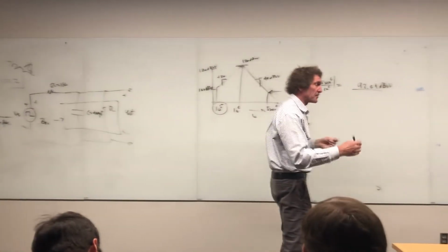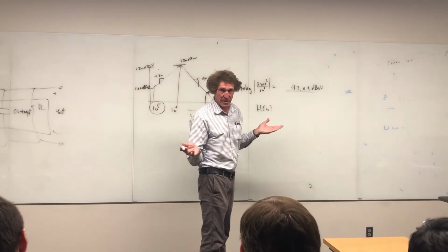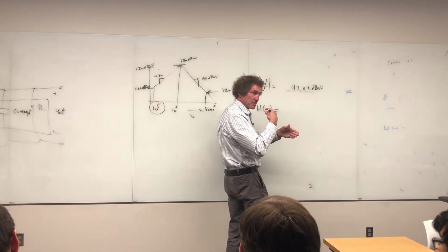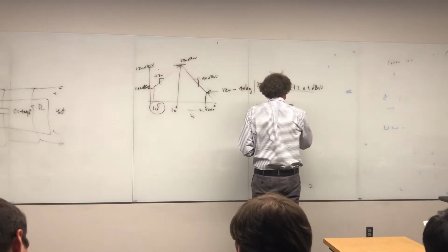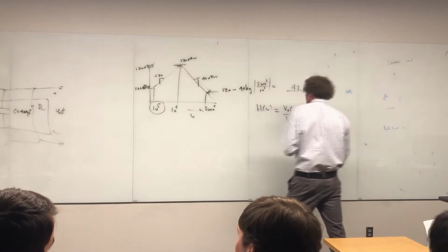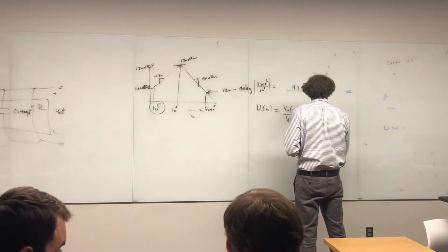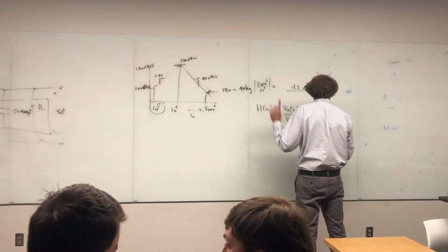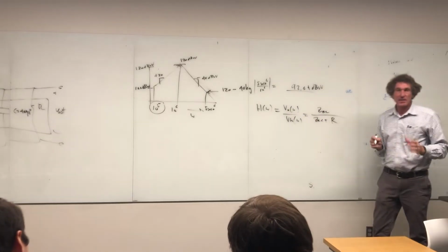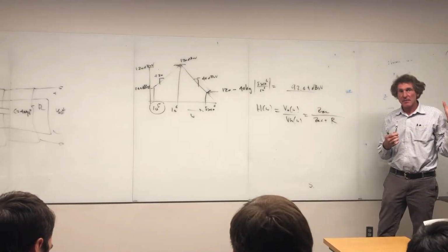Now what I'm going to do, I'm going to get the filter characteristics right here. I'm going to say H of omega for any value of omega, the general one, is actually going to be the ratio of output to input, correct class? Output to input, which is V out of omega over V in of omega. And that's really going to be simply, in this case, just ZRC over ZRC plus R. Now I put it this way for a reason. I didn't put down the complicated form of ZRC that I have over here. I just abbreviated it. Got me, everyone?